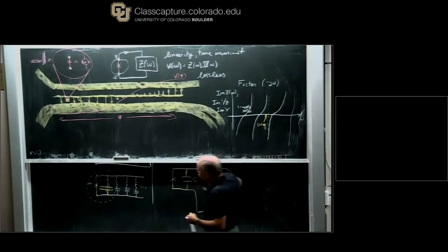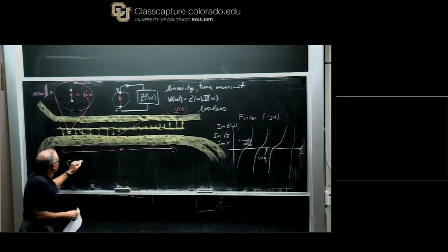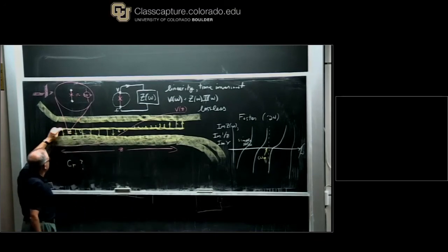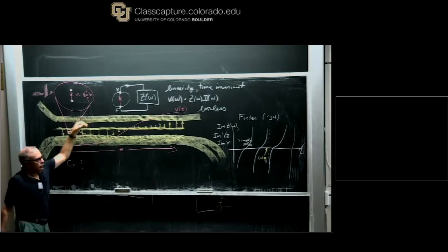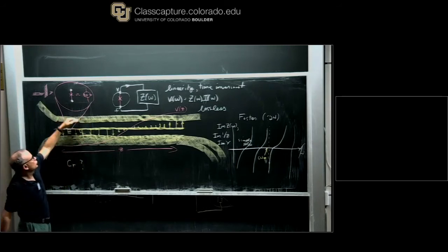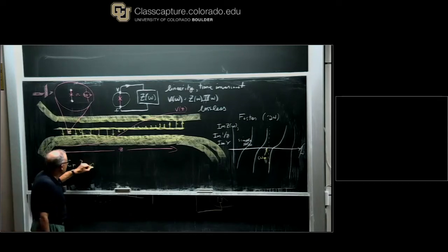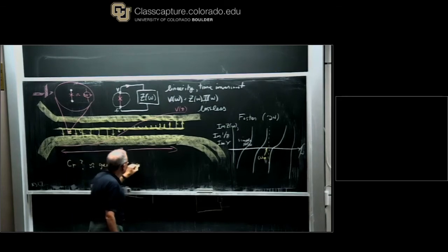Now, there will be a rule of thumb for it, I should say, that this C sub r will pretty much be the following, but special to these 1D resonator structures. See here I've got a parallel plate capacitor, and you might be tempted, well, there's sort of two of them in parallel from this center conductor to ground. And you might say, well, that's the capacitance. And that would be wrong, but it would be correct in that it's one factor that determines the capacitance. It is approximately equal to the geometric center to ground capacitance, what I've just said, times something else.